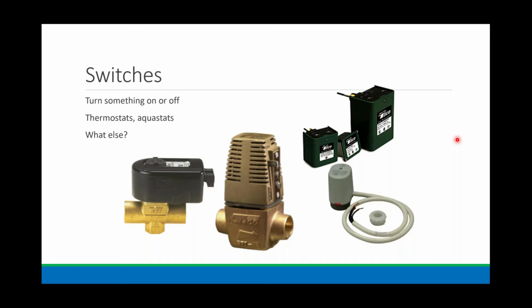And when we close the end switch, we start the next series of power, switch, and load. These little actuators that you normally see on radiant manifolds are generally 4-wire, and they have an end switch. So when they open, they close their switch. And again, we turn on the next series of power, switch, and load.